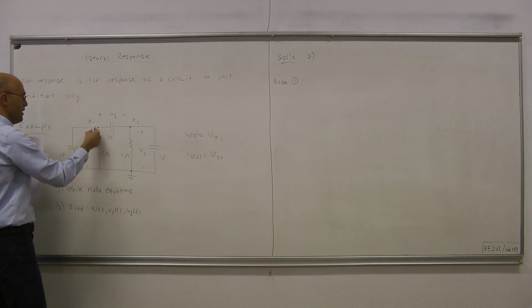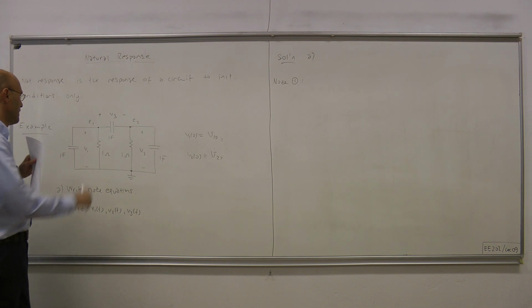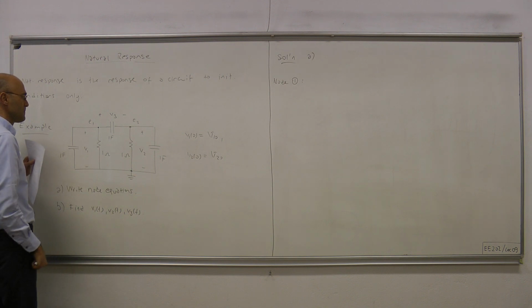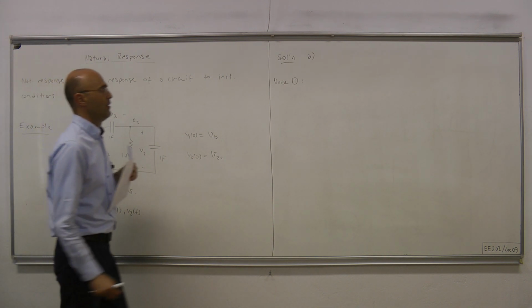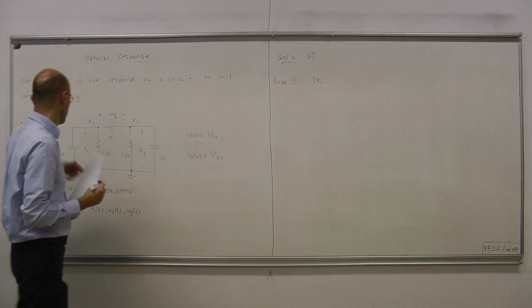We have this current plus that current equals 0 by KCL. This current is C1 dV1, the capacitor current. V1 is E1 and C is 1, therefore we have dE1 for this current.